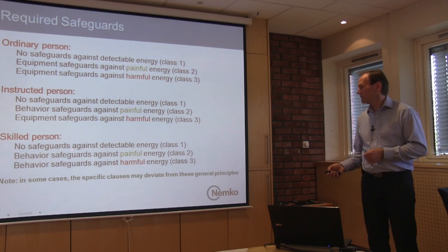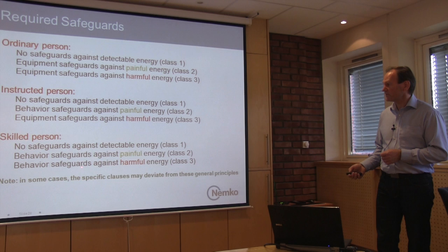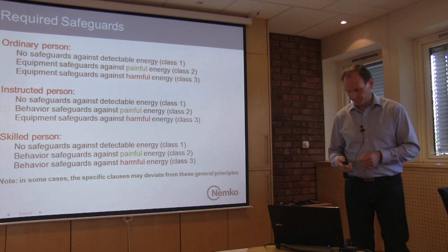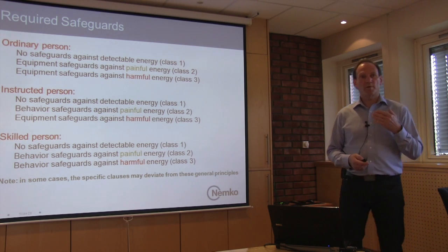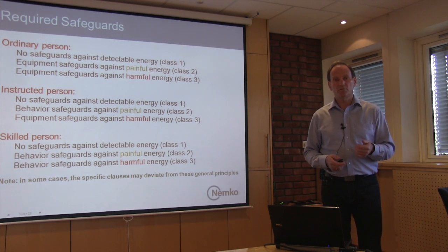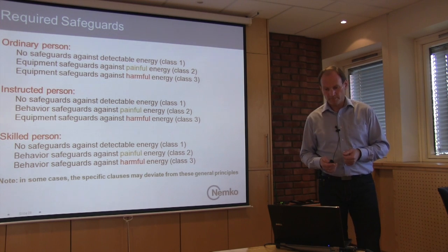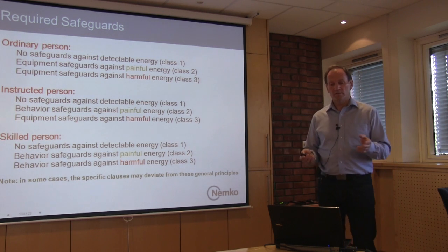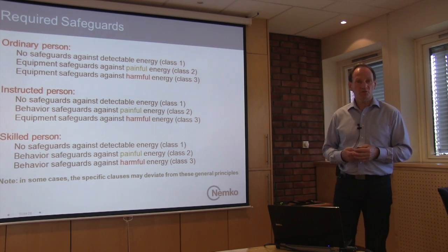But for the skilled person, you don't need an equipment safeguard. You can just have a behavioral safeguard against class 2 and also the same for class 3. So the standard goes quite long for skilled persons related to safeguards, related to behavioral safeguards and instructional safeguards.